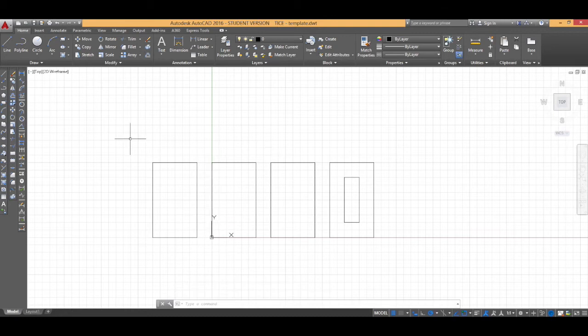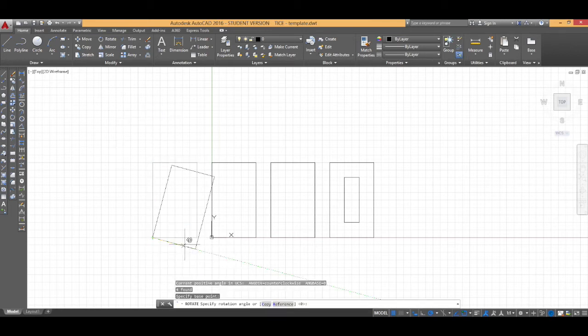The next command that we'll use is the rotate command. Much like copy and move, simply select the object, choose rotate or type rotate, specify your base point, and move according to which way you want to rotate. Let's rotate according to our polar coordinate, -45 degrees.